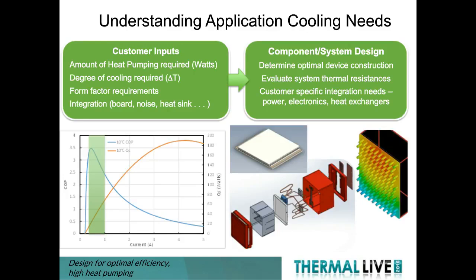So it's very important to understand that while thermoelectrics are perceived as being inefficient, in actuality, when they're used properly and applied properly to the actual solution needed, they can be very efficient at a system level, as long as you do not burden them with additional parasitics, fans, pumps, things like that to move the heat. As long as that's done effectively, a thermoelectric refrigerator can be just as effective and just as efficient as a vapor compression-based refrigeration system.